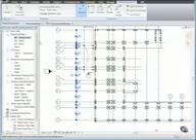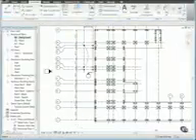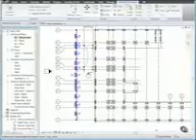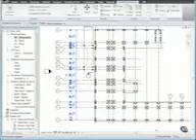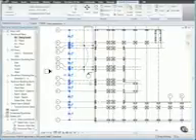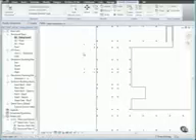Then click Modify and select and relocate the dimension strings if necessary, and zoom into the entryway so that we can create a radial dimension. Clear the selection and on the Dimension panel, click Radial.